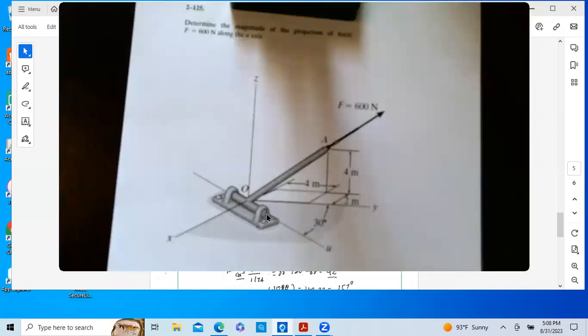Once you know that force, you select the material, and in strength of materials you'll know the stress, and you're easily going to select an area that would accommodate that force. But the first thing you need to know is what that force is. And so this dot product can give us the projection of this force, this 800 Newton force, along this U-axis. So that's the problem that we're looking at.